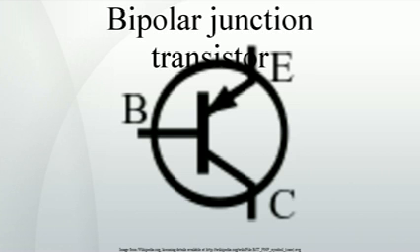Planar transistor, the bipolar junction transistor that made mass-produced monolithic integrated circuits possible. Developed by Dr. Jean Hoerni at Fairchild in 1959. Epitaxial transistor, a bipolar junction transistor made using vapor phase deposition. See epitaxy. Allows very precise control of doping levels and gradients.